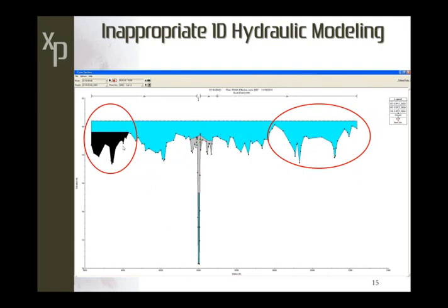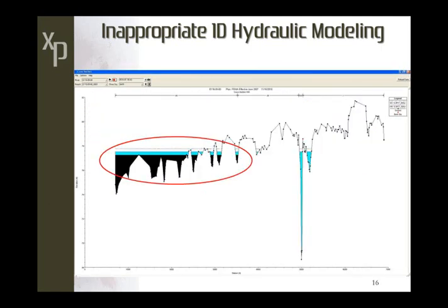So another example, on the left we have a place where the flow area was known to be inappropriate, so it was blocked out, but in 1D modeling you often don't know the extent of the water levels or the flow path until you run the model, and so that blocked out area was obviously not efficient. And on the right again is that same section which only at the very peak of the flood overtops. And the last slide here is probably the clearest example of flow area which is being calculated a little under a mile from our main channel, which wasn't shown to overtop.